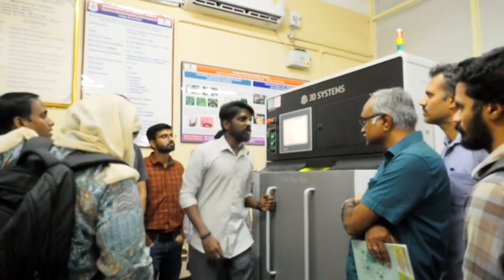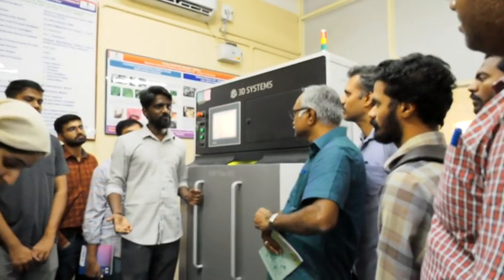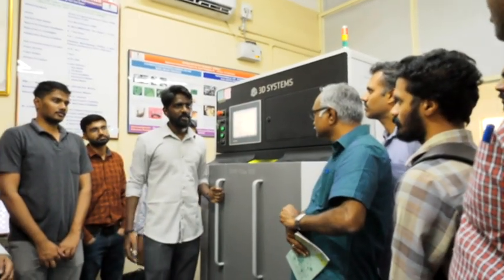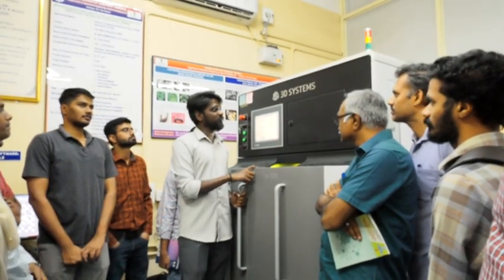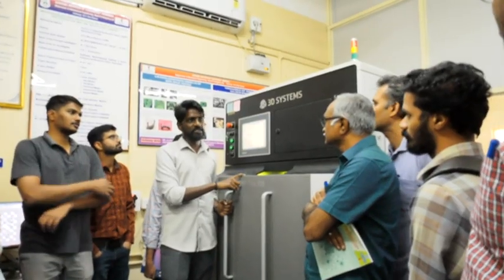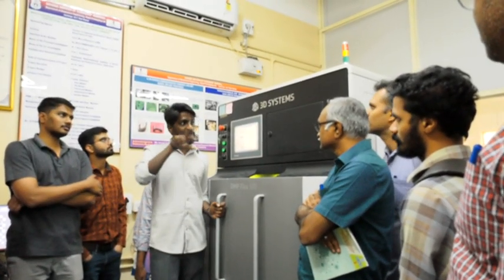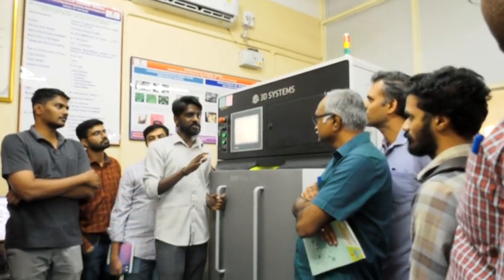Okay, I think you might have heard about LPBF, right? What is LPBF? Laser powder bed fusion. Yeah, okay. This is the machine sponsored by JDL Systems, the DMLS Flex 100, direct metal laser sintering. Flex 100 means the build volume is 100 by 100 by 80, and we are using 100 watts of laser power.